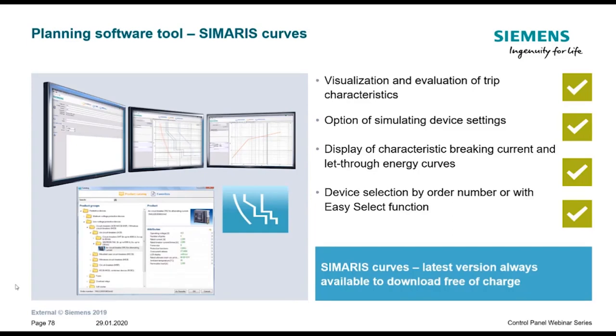One of the good things of SIMARIS Design is that, like I said, you will need the load list and define the infeed network and the dimensions. It will calculate with you a lot of things like load flow, short-circuit level calculation, switchgear selection, cable dimensioning, capacitor dimensioning also, and it gives you an output and documentation that you can hand over to your customer, like single line diagrams, parts list, cable plan, and even selectivity documentations.